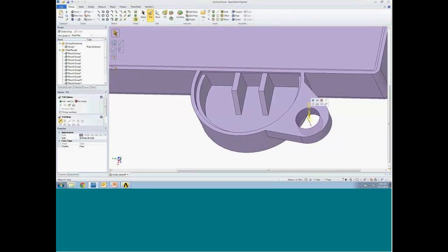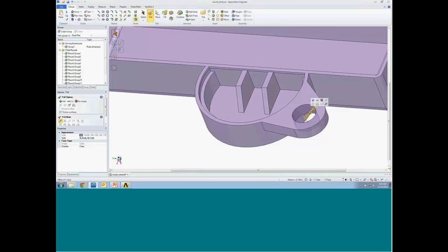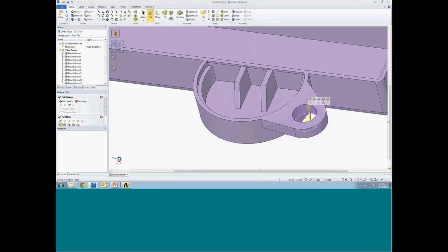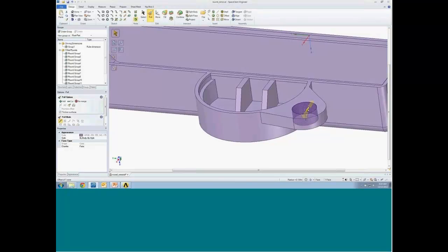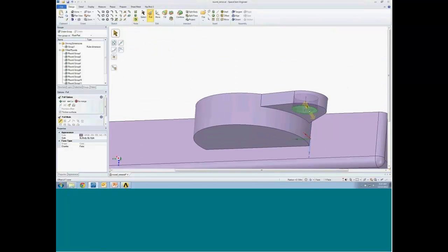Or I won't optimize it, but I'll just show you the integration between the two. Say you want to change the size of this hole and optimize that for whatever reason. Well, the problem is I look over on the left-hand side and see, well, that's not really a pure hole. It's actually just a cone, but it has a very, very slight taper to it. So instead of treating this as a cone, what I might do is say, let's just turn it into a cylinder. Let's just wipe that out.